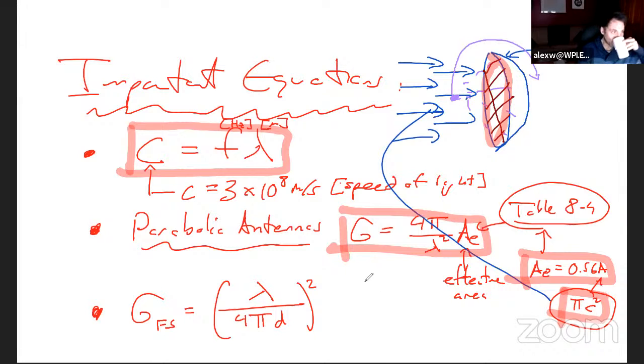And L, some incidental loss. So incidental is if we start off transmitting and already we had a loss at the transmitter, that's what it means, straight out of the antenna, even before the antenna. This is the loss that's incurred or gain of the transmitter system. This is what it is, okay?